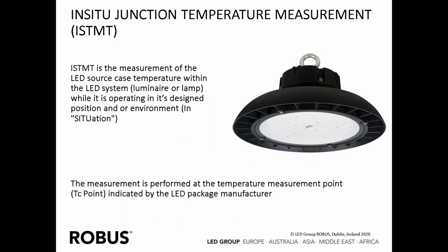What do we mean by in situ temperature measurement, IST-MT? It's the measurement of the LED source case temperature within the LED system, the luminaire or the lamp, while it's operating in its designed position or environment, i.e. in the situation that it's going to be used in.